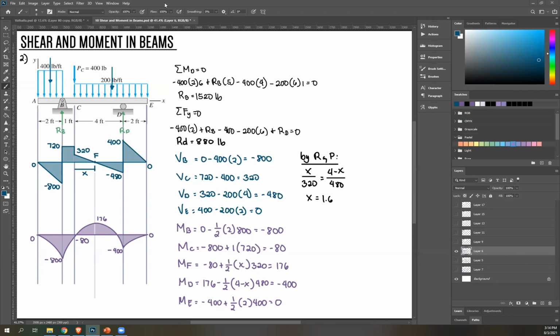Okay, good. So basically, it's just getting the area of the diagram above what you're working on, and then minding your sign. So downward, negative. So your slope also is negative. Below the 0 line areas are negative, and then slope of your moment should also be negative.